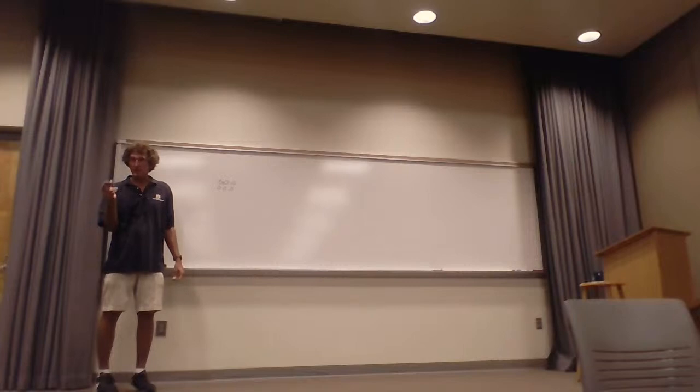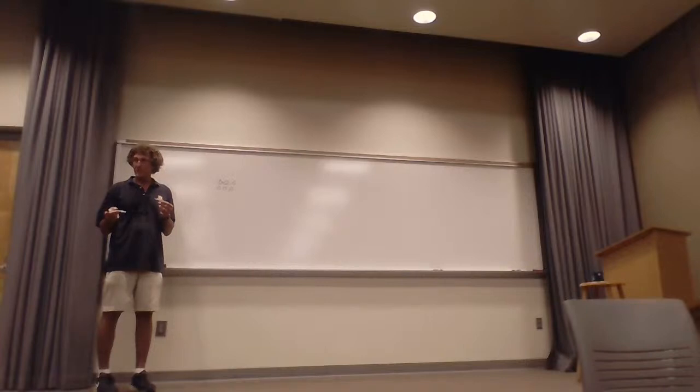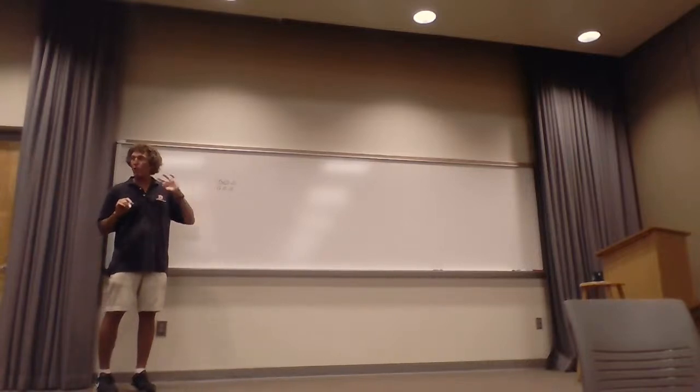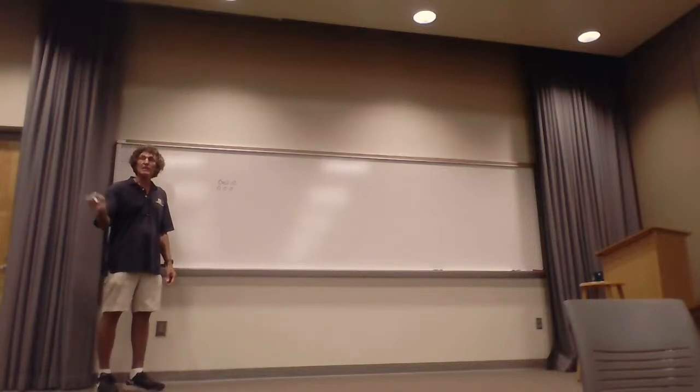I'll show this to you later, but you can figure it out. The area of those is pi a squared, right? The circumference would be n, the number of wires, times 2 pi a. Now, if I said 2 pi a for small wires is compared to 2 pi A, call it cap A, for a large wire, you're going to find out it's a lot more surface area when you have small wires, so that the total cross-sectional area is the same. You're going to have to trust me, I'm not going to bother proving it. Go ahead with the question.